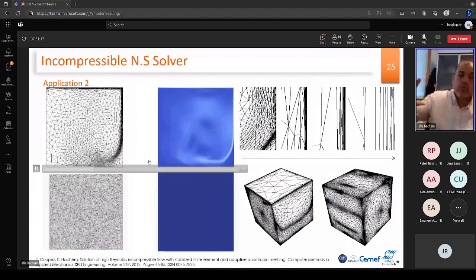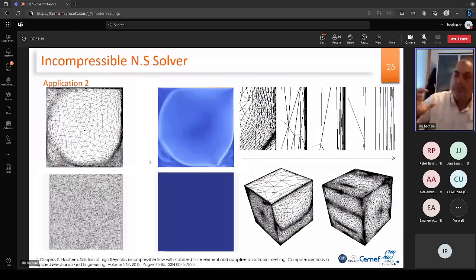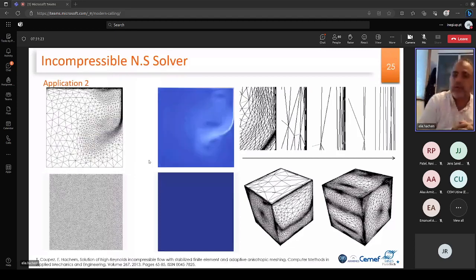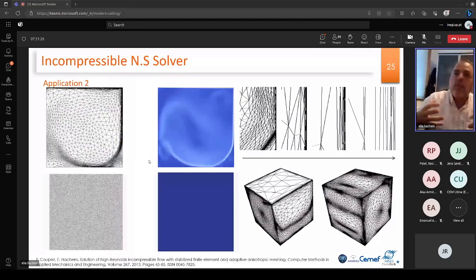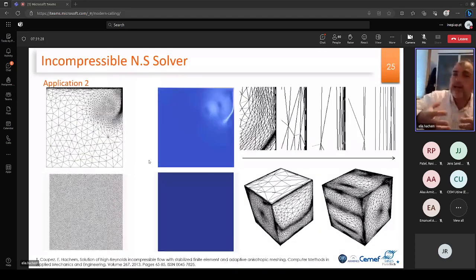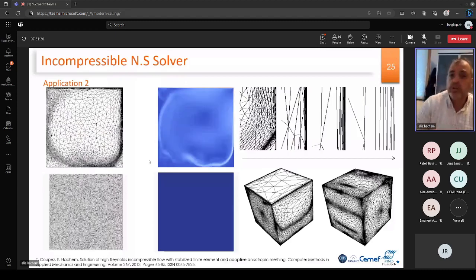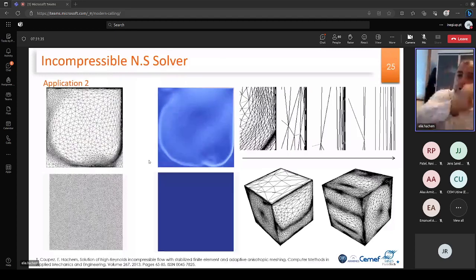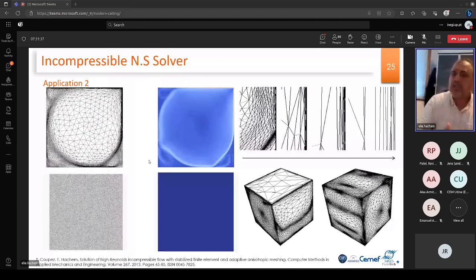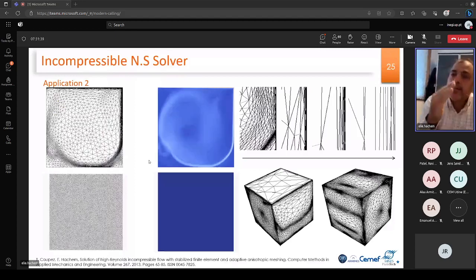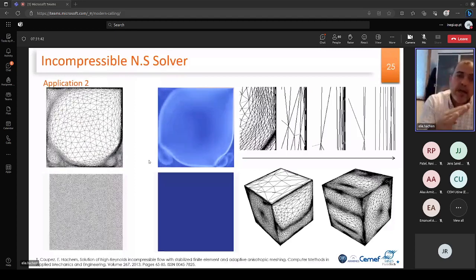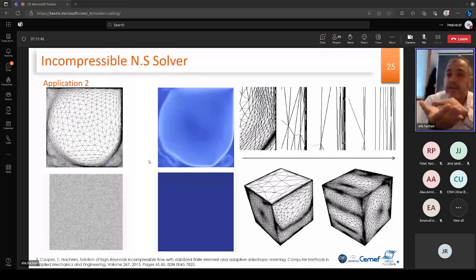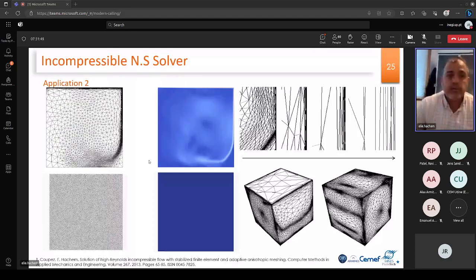So I showed you three numerical tools. The first one is the level set, to transport the material from one side to another. The other one is to solve the fluid inside your part, and even if you want, you can have something outside your part, but it could be just solid, and you are pushing through inside. And the mesh adaptation will localize the interface, separate them, increase the accuracy for high gradients, and at the same time give a very smooth part going outside.